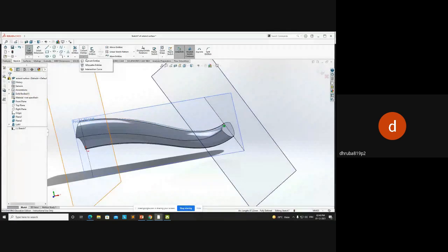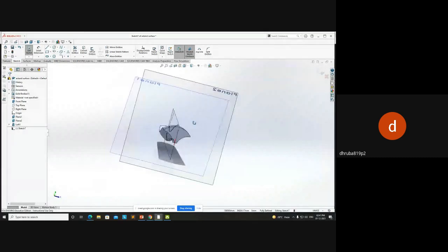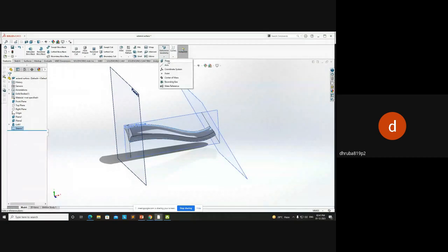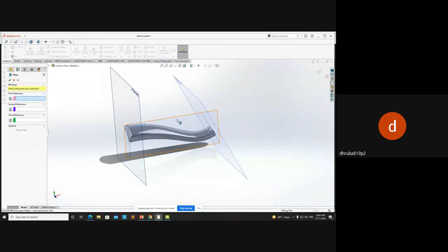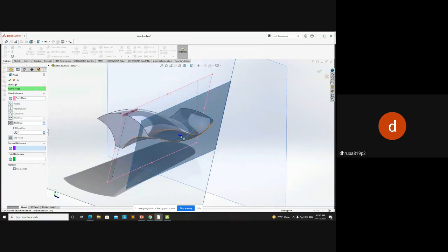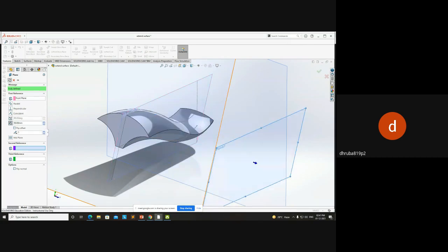So next comes the silhouette entities. What it'll do is cast this shadow onto another plane. Let's say I'll create another plane over here. I'll use reference plane. I'll create one plane. I'll select this plane. I'll discuss this plane creation later. For now, I'm just checking this part.